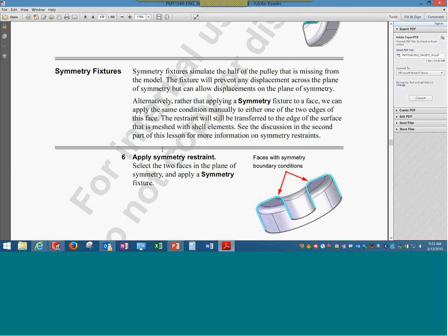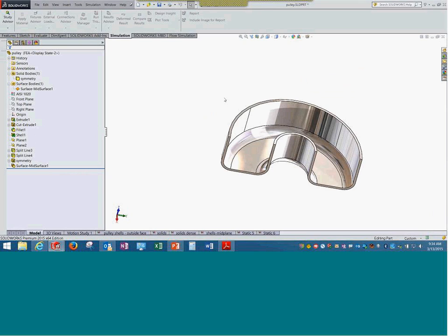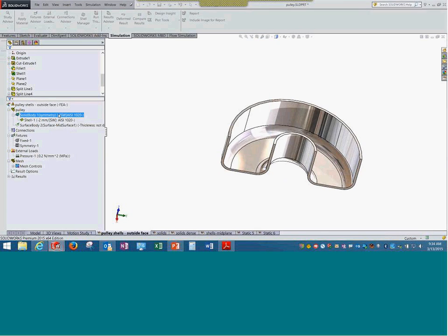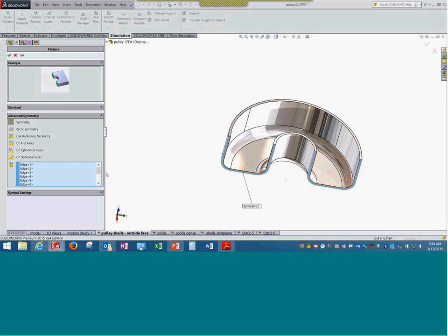So, interesting. Maybe something different that I need to highlight here is more of symmetry. As we saw, the way we treat symmetry in the case of solid elements, when it comes to shell elements, it is a little bit different. Frankly, not much difference, just that we are selecting the edges, and that's it. But if at all we are not selecting the edges and you want to manually give it, then ultimately we need to give a bit more thought in the case of shell elements.